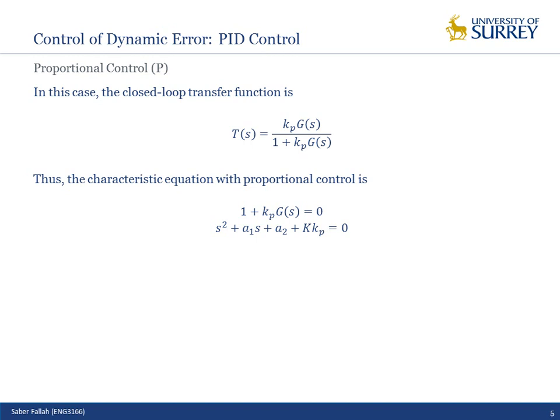For example, a gain margin of 100 means that for the gain K equal to 100, the system is stable. For higher values of K, the system is unstable, or we will have the roots in the right hand side. Look again, by changing Kp, we will change the location of the poles of the system. Correct?